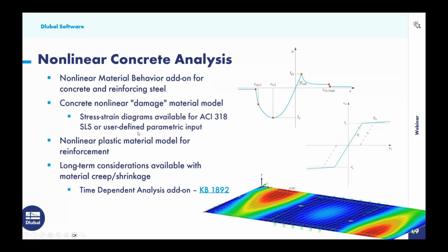So these standards are not so clear on nonlinear design approaches. So this is why we also offer this user defined parametric input for you as a user to define here the stress strain diagram directly. Now, when we talk about the reinforcing steel, a little bit more straightforward, we convert this to a nonlinear plastic material model. We can see the stress strain diagram shown over on the right.